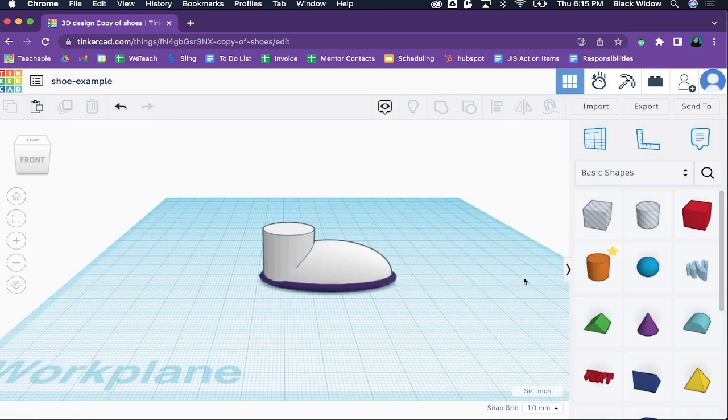From here, you may be tempted to add this file onto your SD card and put it in the printer, but 3D printers cannot read STL files. We must first slice our design to get a G-code file. This G-code file is the instructions our 3D printer needs to be able to print your design.